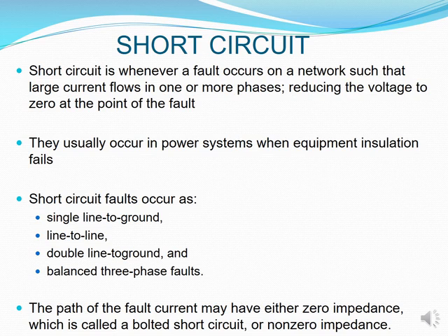Don't forget that you could also have an open circuit that can happen in your line, where you have either one or two of them happening in a system. So your path of your fault current may have either a zero impedance, which is called a bolted short circuit.